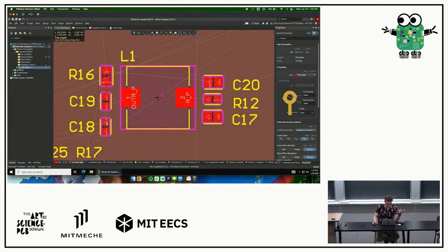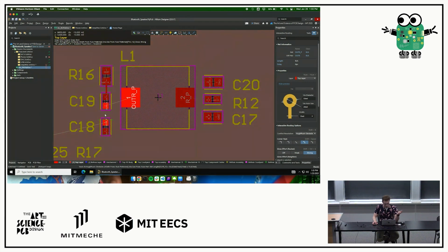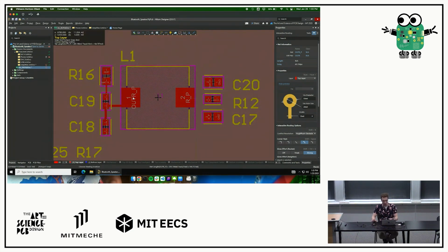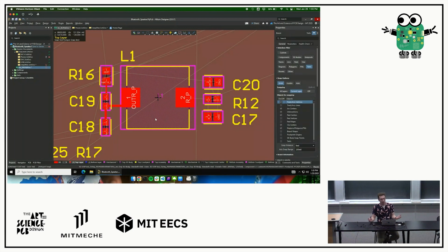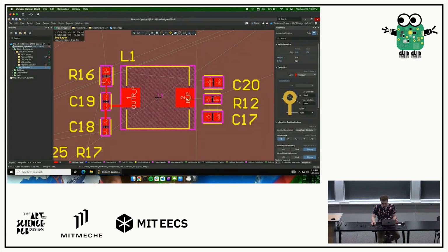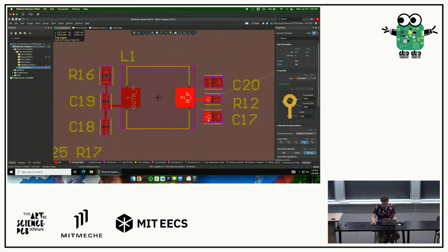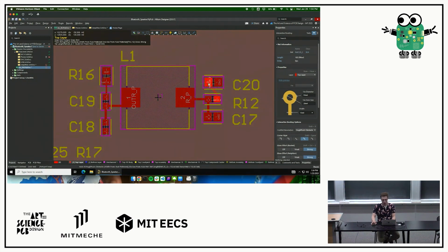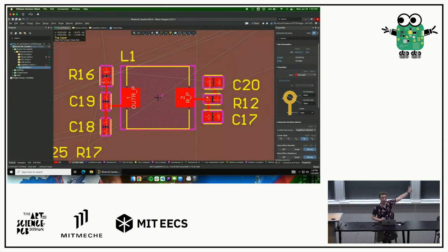But cool. All right, that was two things that I need to connect. Let's try connecting three. So I'm going to click on the top side of this capacitor, and then we're going to go to C19 in order to connect that, and then we'll connect that part to the other side of the inductor here. Excellent. And we can do the exact same on the other side. We can go over here, and then we put that there, and we could even route this part a little crossways too.